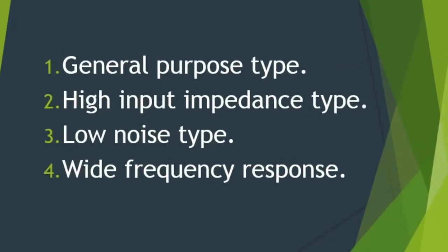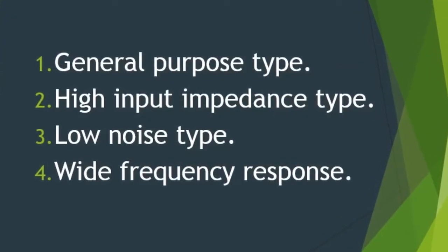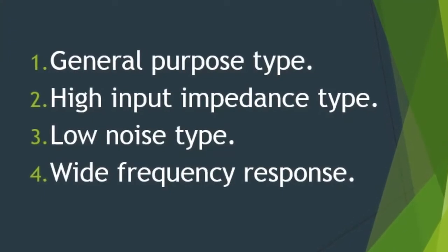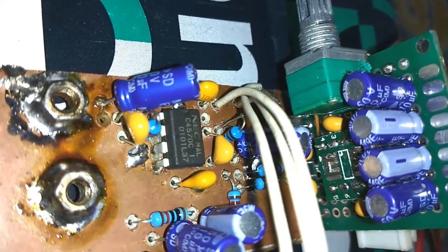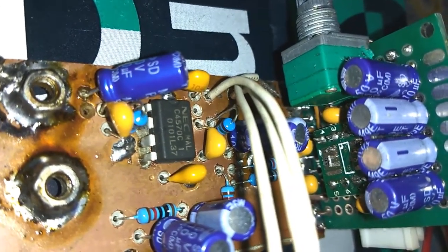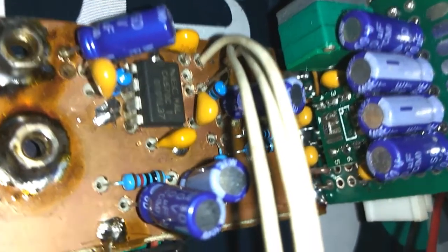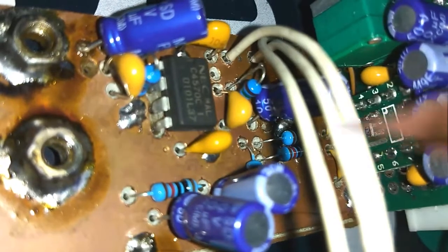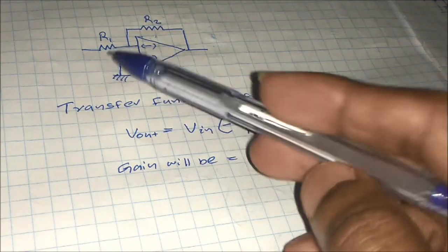You may consider the power supply you have and the package type if you have less space available. In this application, I used UPC4570 IC because the datasheet says low noise, wide band, high slew rate, an excellent choice for preamplifiers and active filters in audio instrumentation.